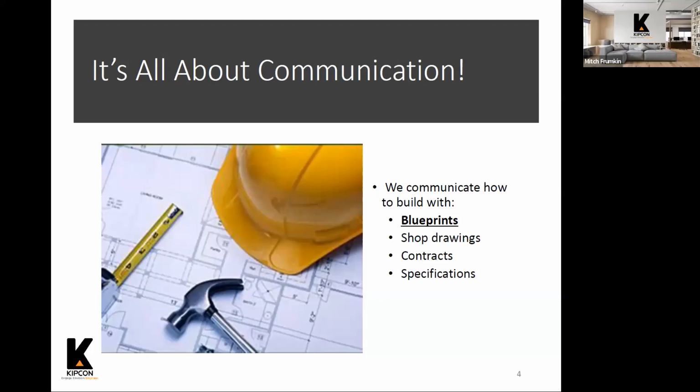Maybe there are shop drawings that need to be included that are generally used when there is something of a more detailed nature that is beyond the set of blueprints that the contractor is working with. For example, there may be an exterior metal stairway that needs to be fabricated, or there is a manufacturer product that needs the manufacturer's shop drawings to give more detail.